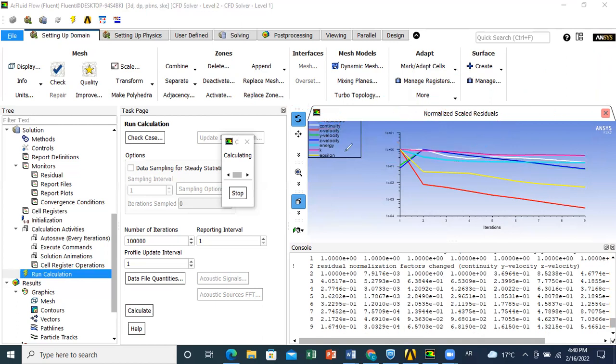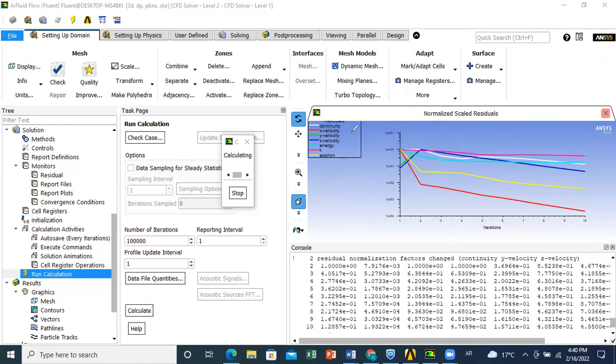The turbulence level will affect the energy performance, the heat fluxes you have, and the type of heat transfer processes. The more complex they are, the more iterations energy will require to converge. But in general, energy is easier to converge than continuity, and you can observe this over a large number of iterations.